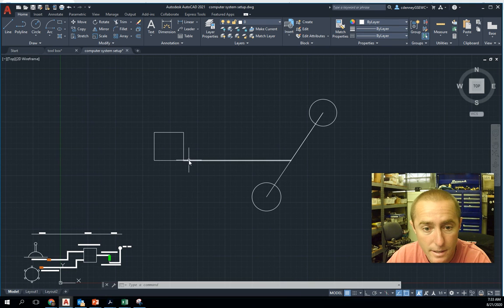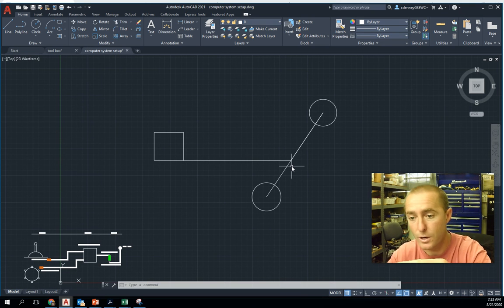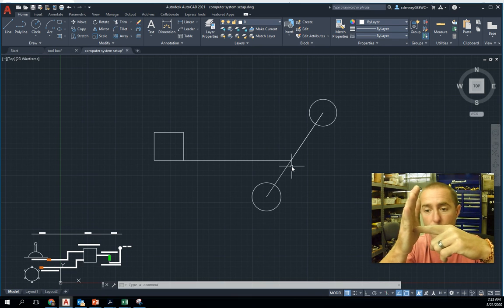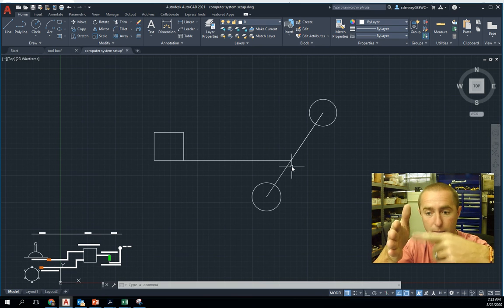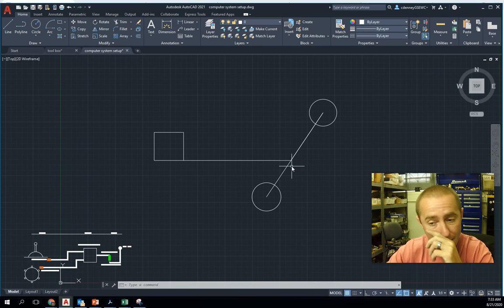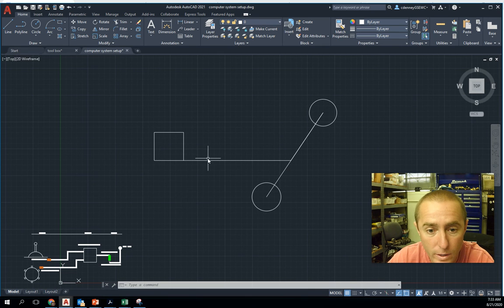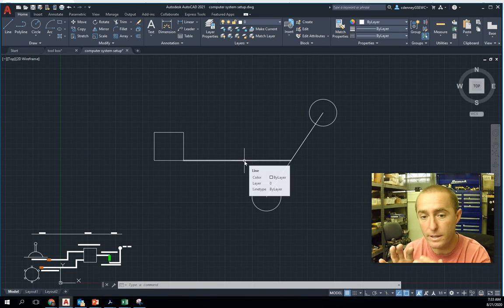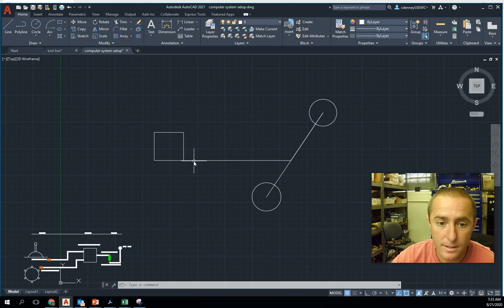The first thing is this is spinning perpendicular to this line. All right, so you're coming in like this, and since this is spinning like this, you want your wheels to spin perpendicular to that. And so it has a unique gearing system that allows motion to come this way to go back out at a 90-degree angle. So it sends linear motion in one direction into a perpendicular direction to your wheels.